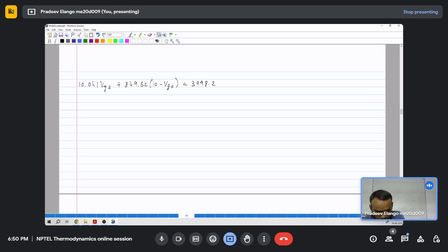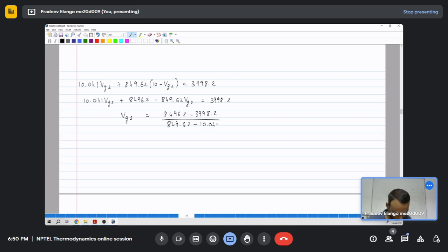So now we have 10.041 Vg2 plus 8496.2 minus 849.62 Vg2 is equal to 3998.2. Now Vg2 is (8496.2 minus 3998.2) divided by (849.62 minus 10.041).